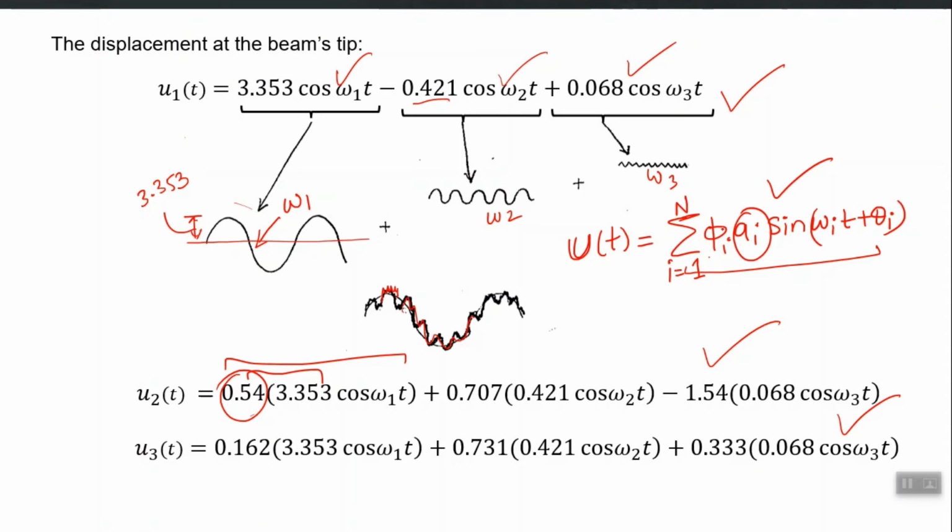And this is the contribution from the first mode, phi I. This whole thing oscillates with a frequency omega 1, or omega I, then omega 2 or omega 3. So each term in that solution is one term in the same summation series, and both solution methods are actually the same. The first method directly derives this expression, and the second uses the transformation concept and the uncoupling concept to get the final solution. Both solutions will be the same, right?